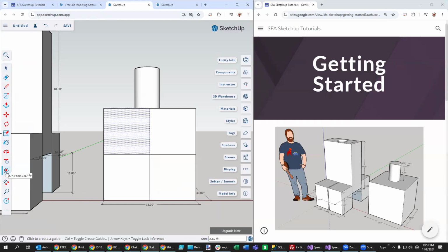We're going to use this measuring tool, or it's called the tape measure. You're going to click right here and then come down a little bit. Let's just go 4 inches. You can see that each time I click and then draw it down here, I can even make it just a weird distance and then type in 4 inches and it'll bring it right back. And look at this. It looks like it kind of snaps into this position. So that's pretty cool. It snaps into 4 inches once we get the process started. So I'm clicking, dragging, it snaps.